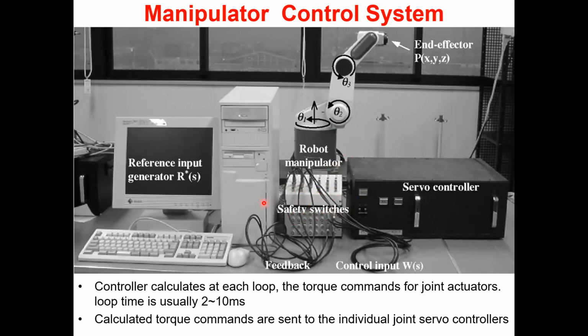Whenever you operate the robot, before you send the command to start the operation, you need to have your fingers on these switches. Just in case you see any bad noise or any vibration, you need to turn off these switches. The moment you do that, these control signals will not go to the actuator and the robot will freeze. Okay. So that is how it happens.